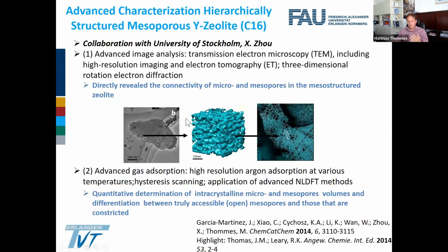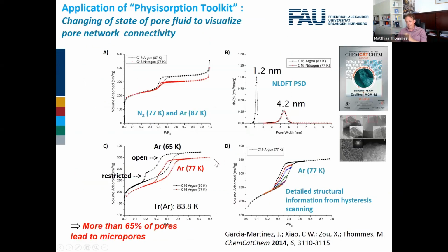but it's not possible to quantify this sufficiently just based on this kind of electron microscopy approach. So now we couple this with advanced gas adsorption, high resolution argon adsorption, with hysteresis scanning and so forth. And this allowed us to determine the intercrystalline mesopore volumes and differentiate between truly accessible mesopores and those that are constricted. And this summarizes my talk very much.